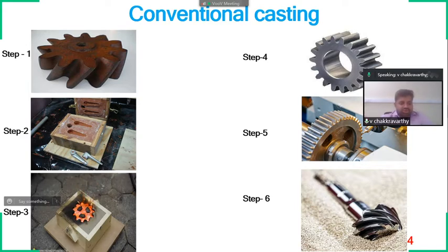Why do we need to use the material judiciously? Why don't we go for casting itself? Those questions may arise in our mind, right? Say, for example, we are taking a material like titanium 6Al 4V alloy, which is one of the most popular aerospace alloys right now. That kind of material has a very poor thermal conductivity, in the range of 9.5 watts per meter Kelvin. Such materials are very tough to machine.